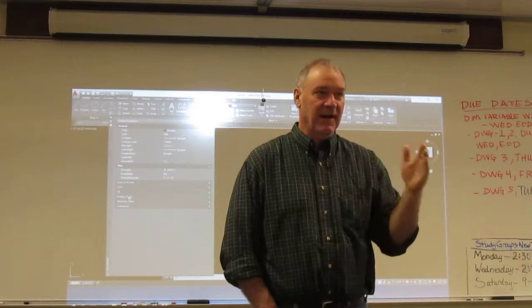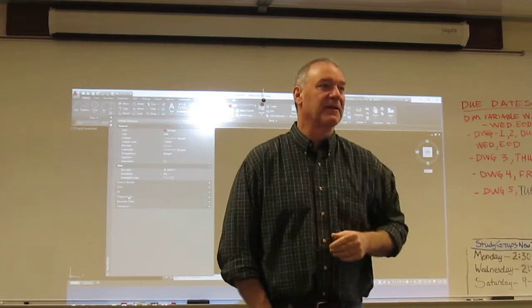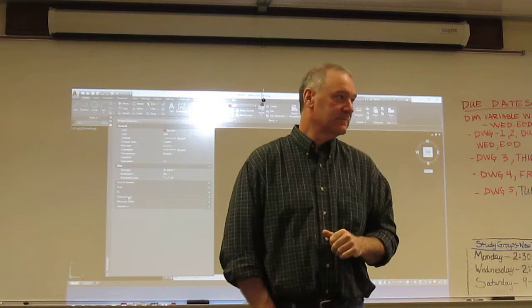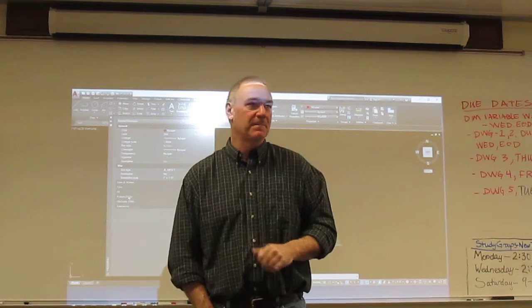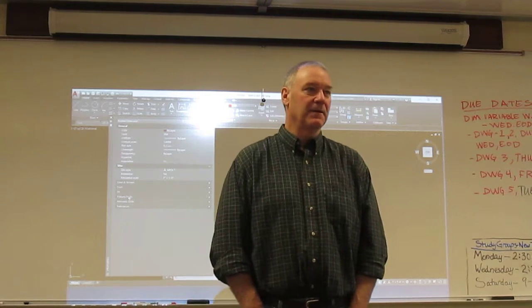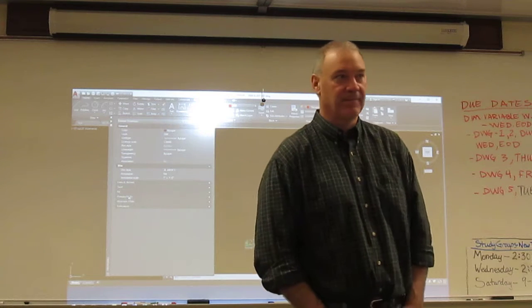I'm looking at, can you get those 1/8 inch? Can you get it a 1/2 inch off? Can you get all those variables set up so that it is to standards? There will be multileaders on it. There's a negative cylinder. It will be a 2-scale drawing. So in essence, you'll pop the drawing open. You'll have to create a dim style and multileader style to our standards, and then apply those dimensions.